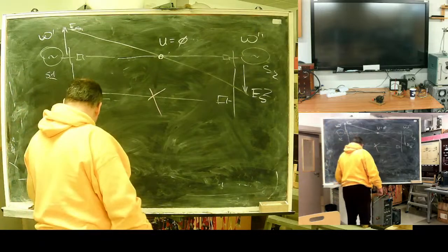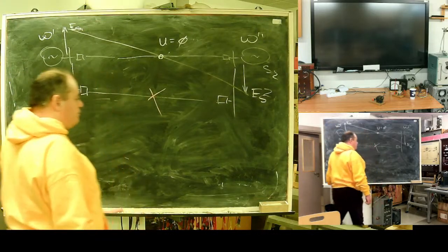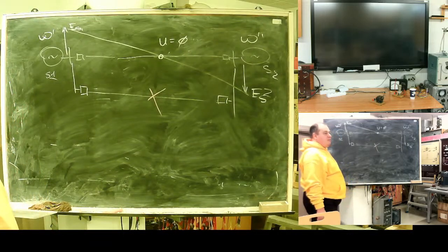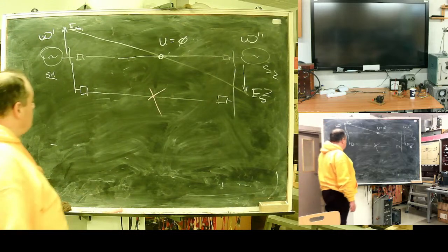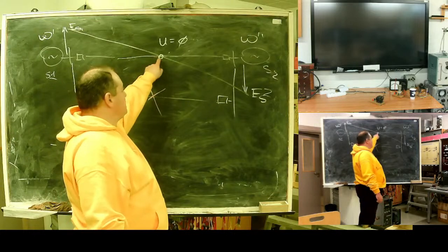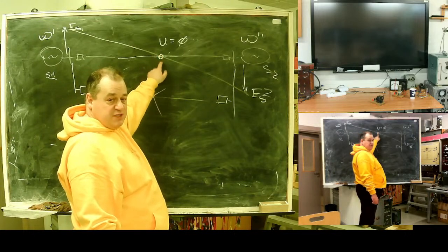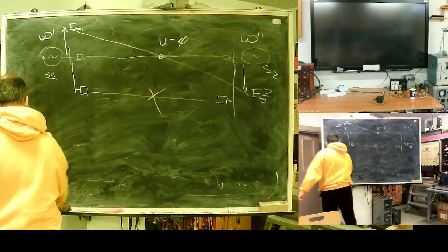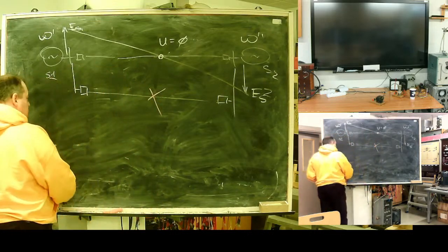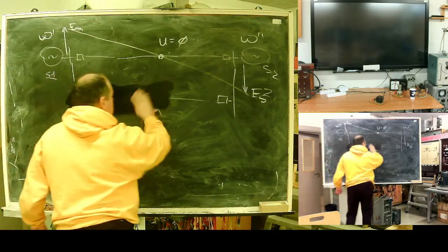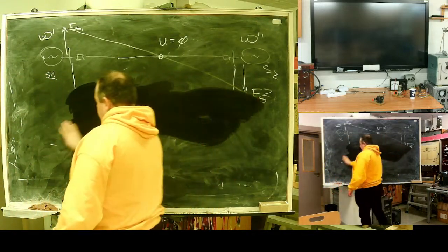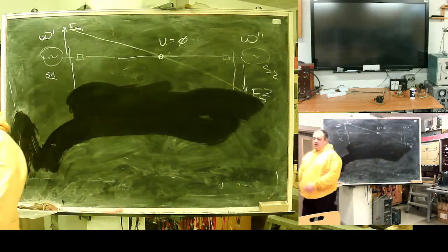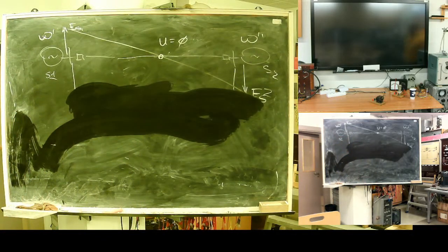It's a very bad idea. But it's a kind of nature-born problem of distance protection. In case of power swing, distance protection thinks that the center of swings is a three-phase fault. To prevent such operation, all real distance protections are equipped with a special blocking logic, preventing operation